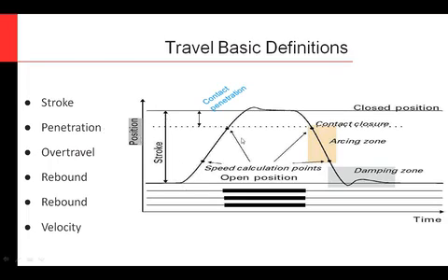You'll hear something called penetration or wipe. This is where you measure from when you first make contact, so as it's traveling, where it first makes contact, till the final resting position when that circuit breaker comes closed. So you want to make sure you have enough contact here so current's flowing adequately. Something you'll see is over travel, where now the circuit breaker travels past the fully closed position, goes up, and then comes back and comes to rest there.